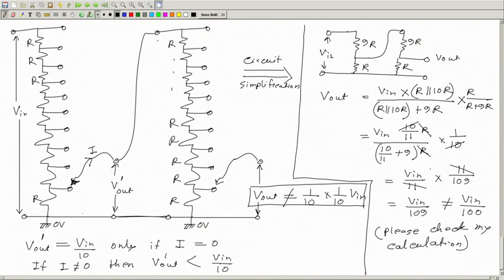And then, if we assume there is no loading effect here, if we just have an ideal voltmeter or potentiometer connected here, so no current is flowing, then this part will give 1 by 100, that is for sure. V out is equal, sorry, 1 by 10 of V out prime, assuming this current called I1 is equal to 0.